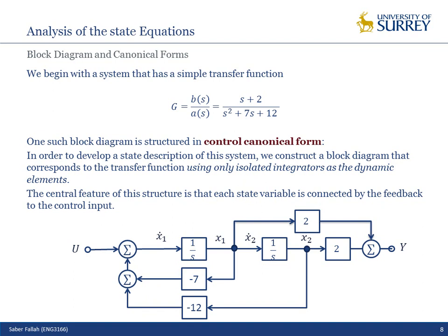Look, what I've done so far, I'm given a transfer function. Based on the order of the characteristic equation, I define two integrators, because I have a second order differential characteristic equation. The output of each integrator is my state. And I give a negative feedback to the first integrator plus the input. So here I built up my characteristic equation.